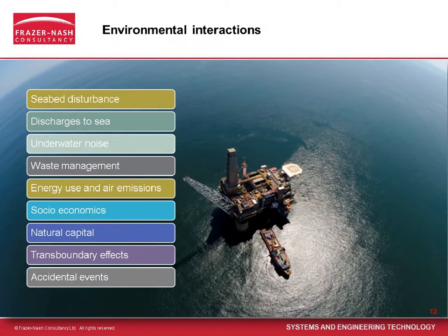During the MID workshop, it's useful to start with a baseline of environmental interaction areas that should be considered. This can be at a high level to prompt workshop attendees' thoughts on potential environmental impacts and risks that may arise from each activity. For example, you're likely to get seabed disturbances as a result of burial of existing infrastructure, or remediation of the seabed, or as a result of excavation techniques. You may need to consider underwater noise as a result of the use of explosives, as a result of rock dumping, or because of underwater cutting or tool operations.